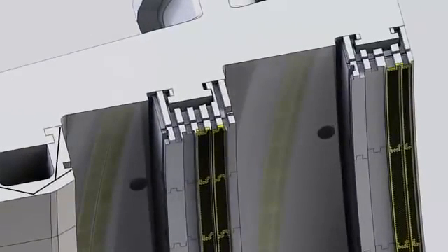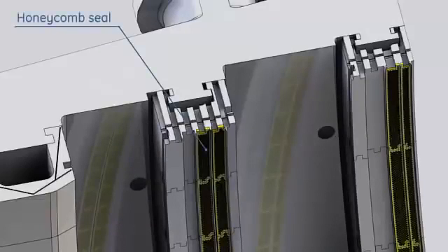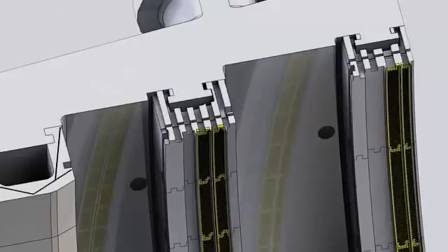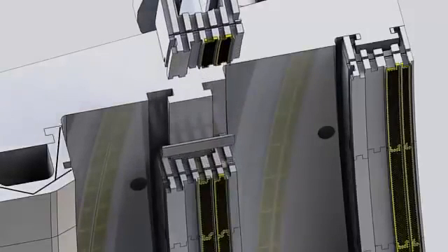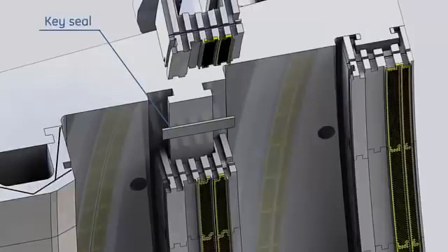The second and third stage shrouds have teeth that mate with teeth on the tip of the second and third stage buckets. This labyrinth seal minimizes tip leakage. For better tip clearance, a honeycomb seal is integrated on the second and third stage shrouds. This honeycomb is relatively soft material. The cutter teeth on the tip of the second and the third stage buckets open a slot on the honeycomb seal without any material transferred, providing tighter clearances to improve the unit efficiency. Shrouds of the last 2 stages are sealed by interconnecting tongues and grooves and by key seals.